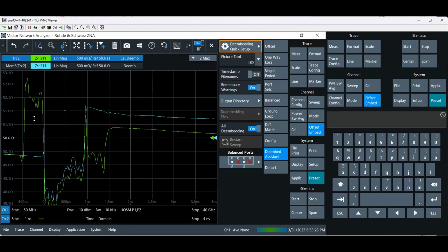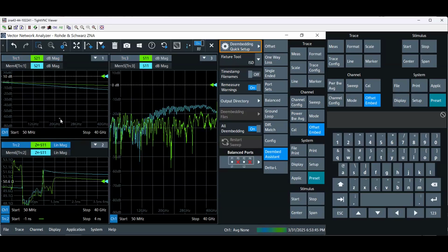Because our DUT has the lead in and lead out structures with different impedance, you can see the effect on our measurement results with the impedance correction and without the impedance correction. So, yep, this is all the live demo I had to show the results of the de-embedding, with and without impedance correction utilized.